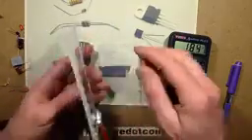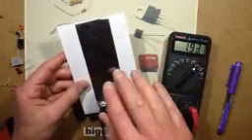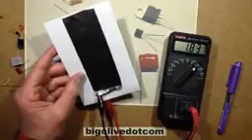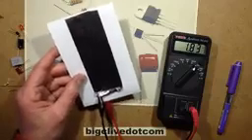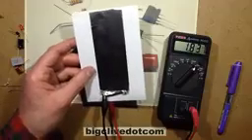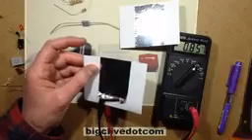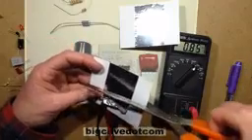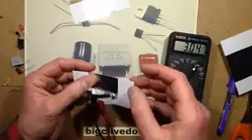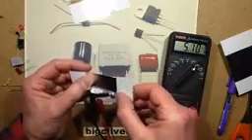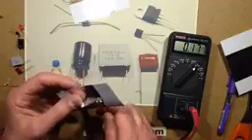And to prove that the area of the foil affects the capacitance, if I get a pair of scissors and cut this in half right now, it's 1.83, if I cut that in half, it's half the capacitance, it's now 0.8, and if I cut that again in half, it'll go down to about 0.4, which it has. So that's basically how a capacitor works. It's an insulator with 2 metal plates on either side, and the area of the metallization and the thinness of the separator is what determines the capacitance.